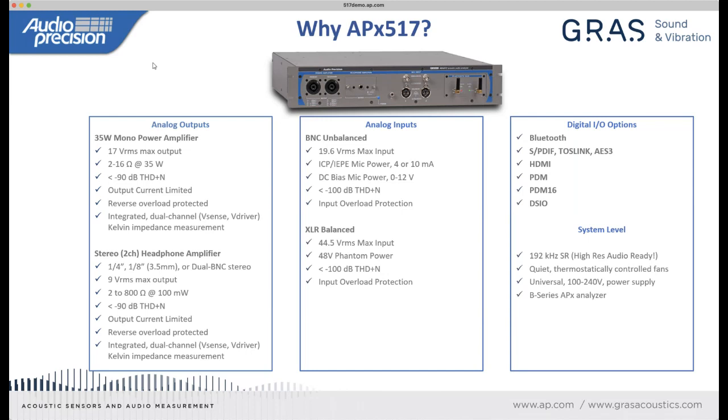So specific to the task of measuring a microphone, the first thing we have, on the left of the front panel that you might be able to see, is a power amplifier. And we're going to use that today, not because we're going to measure a speaker, but to drive what we would call a source speaker, the device that's going to provide the acoustic stimulus signal for our measurement microphone.